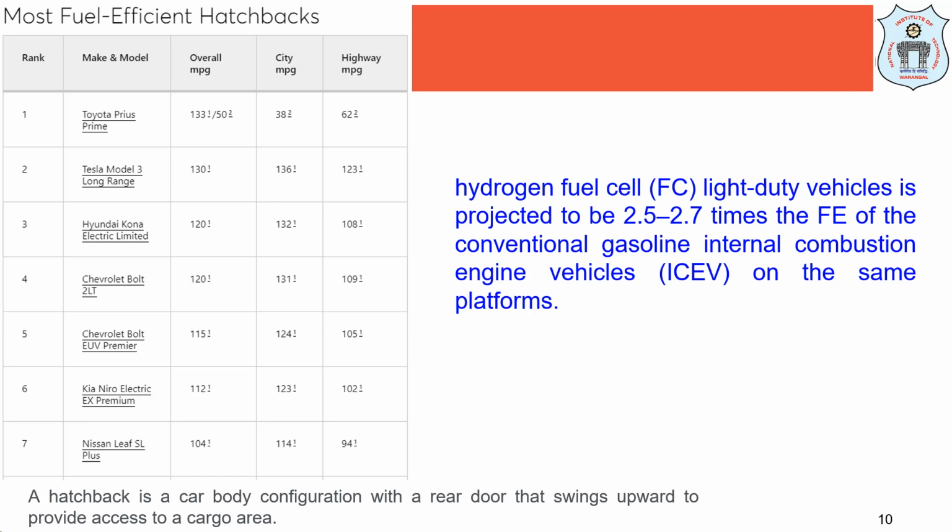Even with lower efficiency, because right now we are operating these fuel cells with less efficiency, right? We are getting a higher power density at 0.6 volt per cell than the base case of 0.7 volt per cell. At this rated power point, these hydrogen fuel cell vehicles are projected to provide essentially the same fuel economy multiplier.